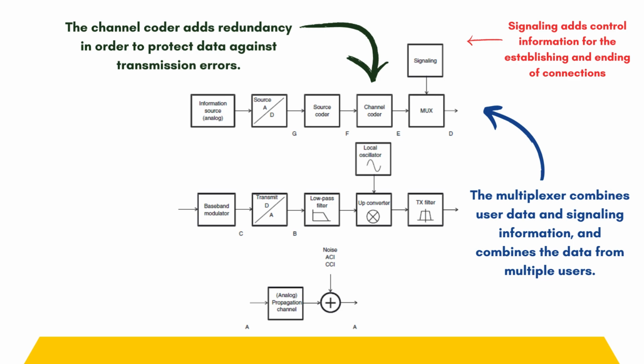The transmitter side local oscillator provides an unmodulated sinusoidal signal corresponding to one of the admissible center frequencies of the considered system. The upconverter stage is used to convert the analog filtered baseband signal to a passband signal by mixing it with the local oscillator signal. The RF transmit filter eliminates out-of-band emissions in the RF domain. Even if the low-pass filter succeeded in eliminating all out-of-band emissions, upconversions can lead to the creation of additional out-of-band components.